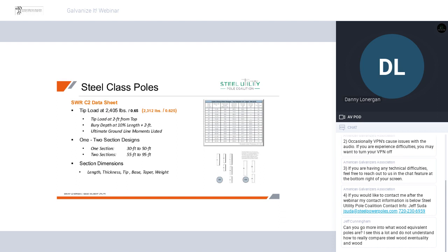So usually the diameters, the tip diameters, and then its tapers, those are pretty important for constructability and sizing brackets, mounting, gains, things like that. Section lengths, somewhere between 55 and 60, maybe 65. Most designs evolve into 2 sections for a couple different reasons: ease of fabrication in respective shops, ease of galvanization in respective tanks, and then ultimately effective transportation.